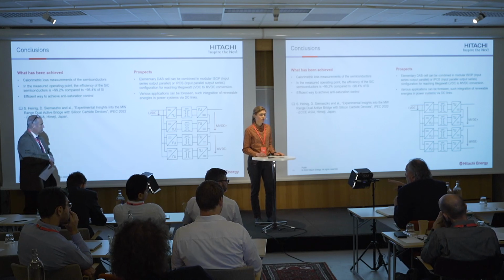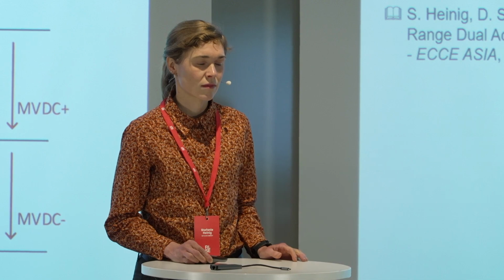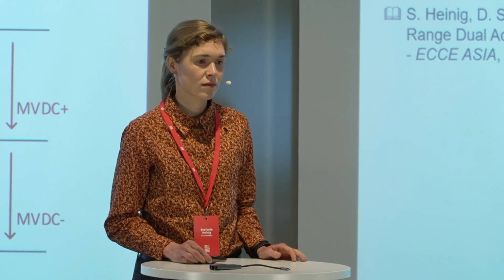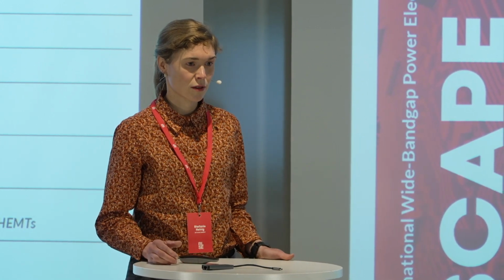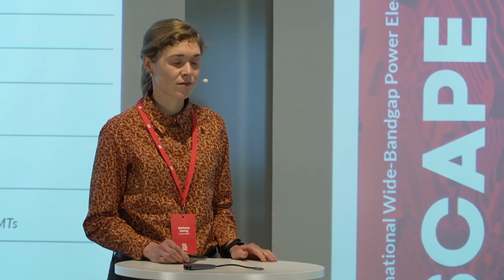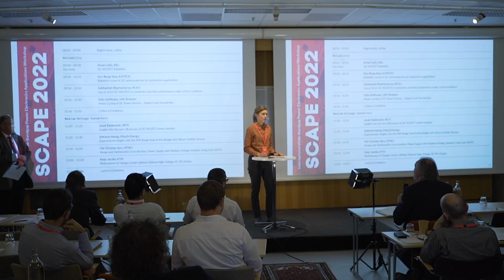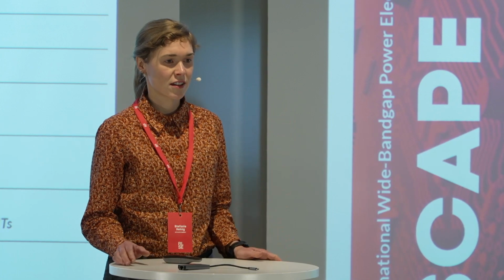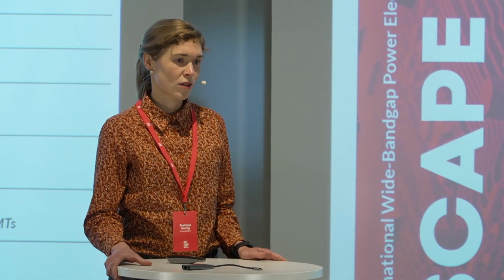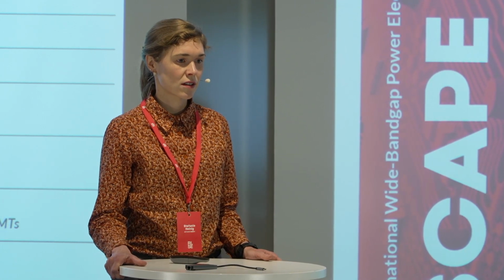If you work with 2 kilovolt, you can basically cope with the size of the transformer as you have shown. If you go now to, let's say, 10 kilovolt, the design was for 10 kilovolt. Okay, so all the spacings and isolation, and partial discharge are already designed for 10 kilovolt. Okay. And for the lightning impulse, the test voltages are standardized, so we have to go even higher then. Okay, thanks.